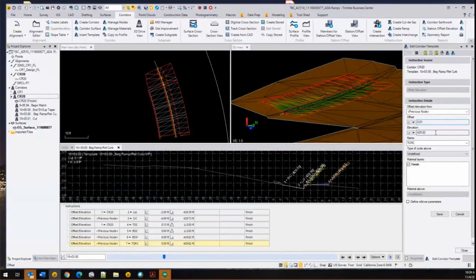So I don't think you can, and I never do, build things directly above one another, whether that's in station or offset. So I put this retaining curb 100th outside the back of sidewalk. So now I'm going to add the back 0.49 out so that the ultimate offset is the same.